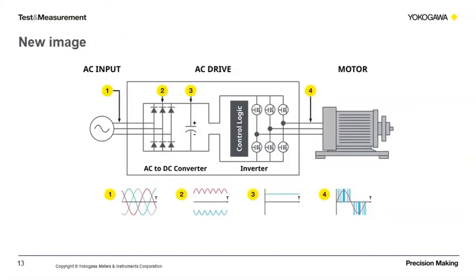Harmonics have only been around over the last few decades since the introduction of electric drives for motors, fans and pumps, and power supply switching circuits such as rectifiers, shown here as part of the motor controller or AC drive. An AC motor drive has AC inputs that cuts and chops the input sine waves at the input, then converts the chopped AC waveform to DC, resulting in a waveform at the output that has much more signal content than the fundamental waveform that it started with. This cutting and chopping and filtering results in harmonics and distortion.